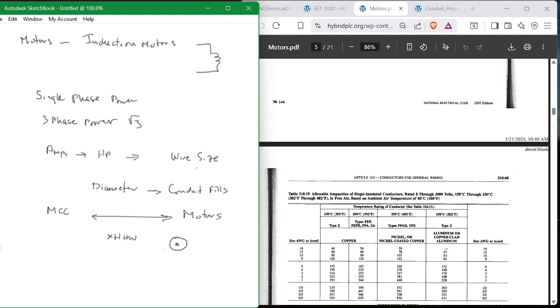They just melt away, and others don't. And this is one that just kind of cooks in place. So you can decide which one to use. Now, I'll tell you something about XHHW insulation. It's not the kindest insulation to strip. Electricians hate it. With other kinds of insulation, they have these wire strippers and it comes right off. XHHW, you really have to work at it to get it off.